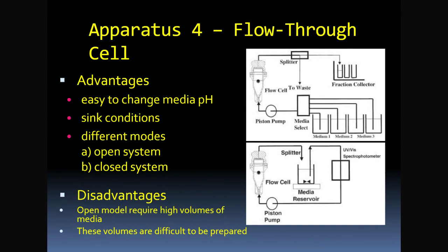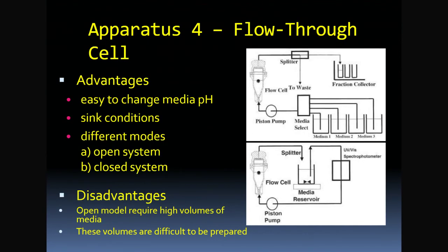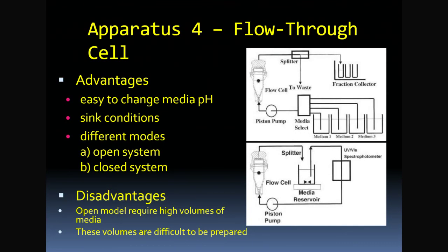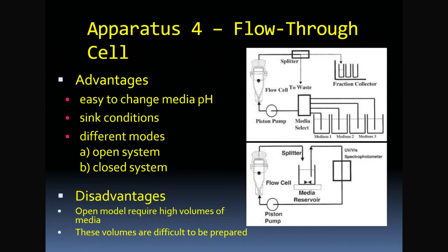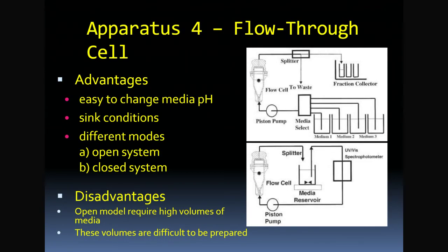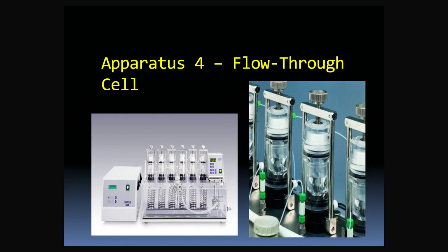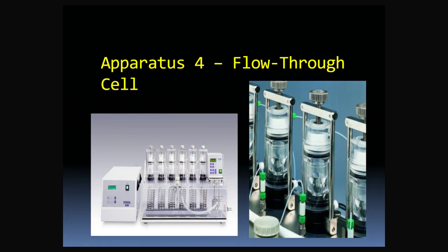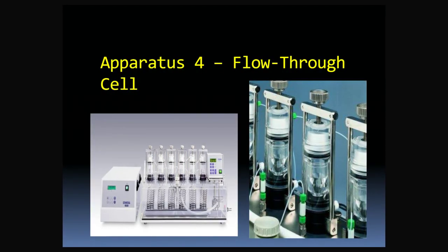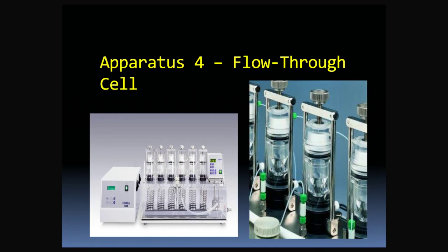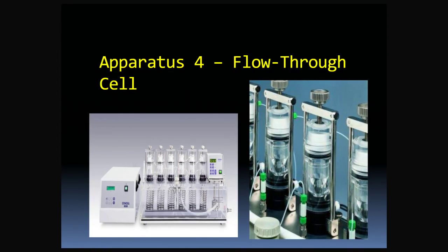Evaluate the hydrodynamic flow. How would a fluctuation in the piston pump stroke volume directly impact the thickness of the stagnant diffusion layer at the particle surface? Observe the vertical architecture of the flow-through cell, where the solvent is pumped from the base upward to establish a consistent fluid flux over the solid dosage form.